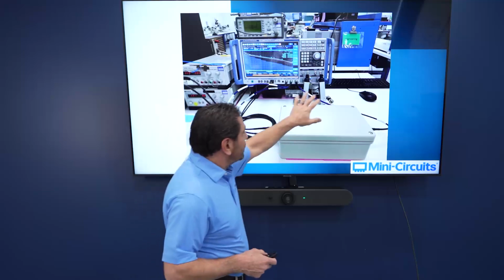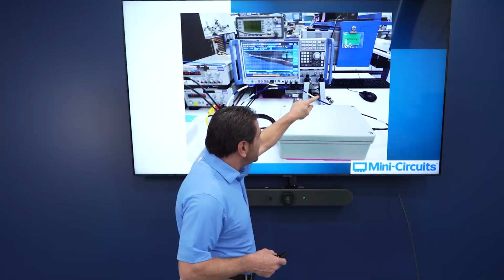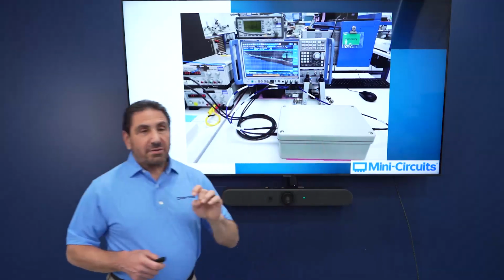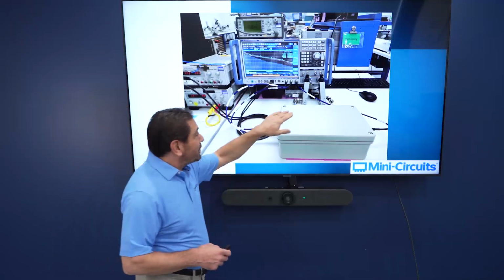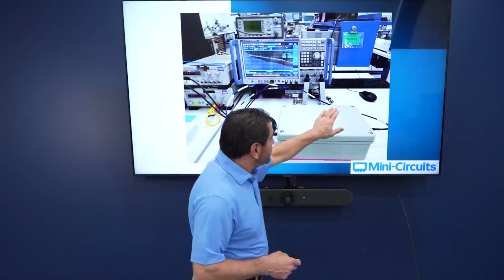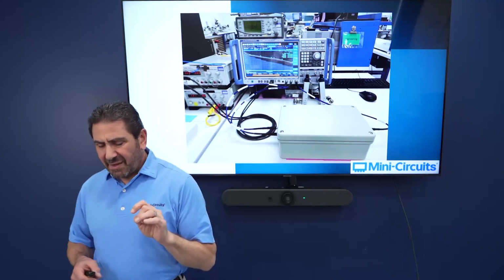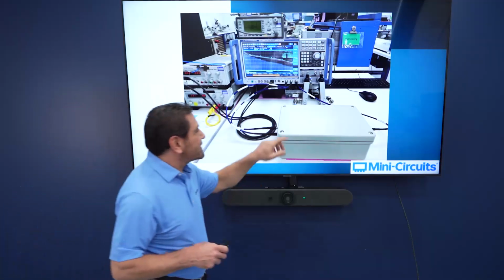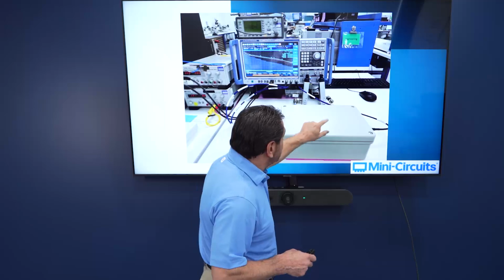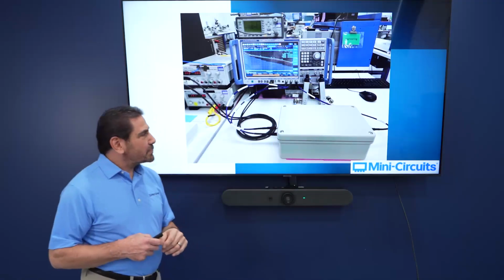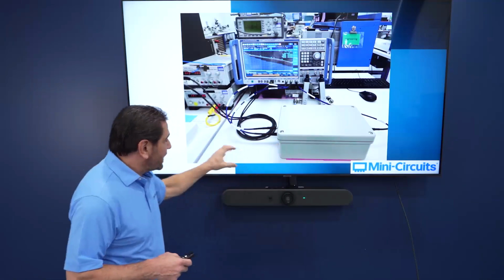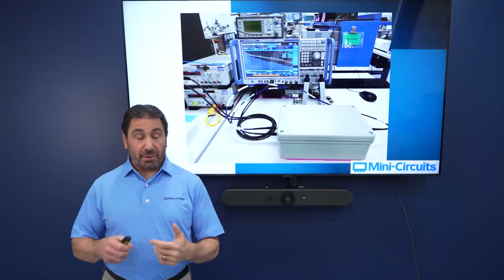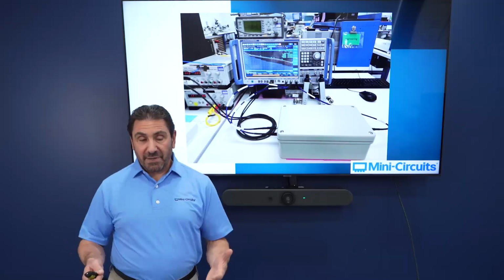The other thing you'll notice, and we'll go into this front end a little bit more, is that there are very short coaxial cables, well matched, phase stable, that run into the EMI enclosure and back out again. It's very important that we minimize the total phase length from the output of the analyzer back into the input, and you'll see why as we go through this. What's not shown here is that the AC power that powers all this is coming from a conditioner and filter, because we don't want AC noise, again, corrupting the measurement.